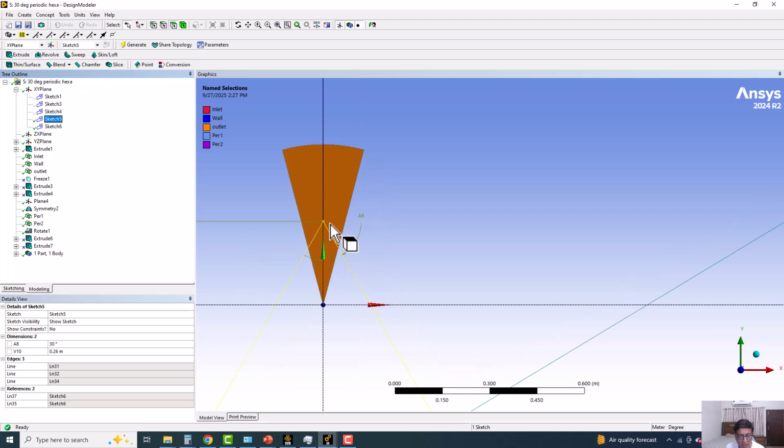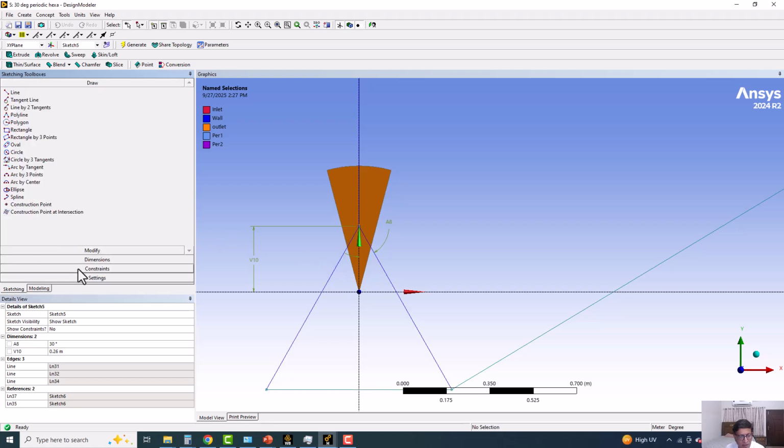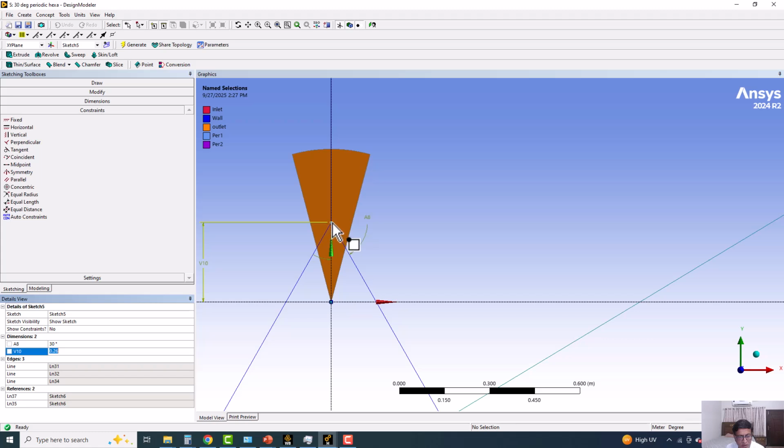Okay. The one sketch is at the, I tried different angles. I started with a 50 degrees angle from the y-axis of the one line, and then I made the constraint here, and that constraint is a symmetric constraint which I applied on these two lines. The symmetric constraint or symmetry constraint. So this line and this line will be having the same angles. So there's no need to define the dimension like angle for both of the lines, but for only one line, and then put the constraint for the symmetric boundary condition. And also I defined the height of this point from the x-axis.